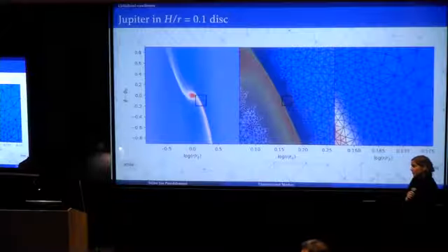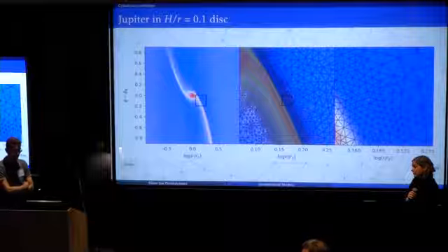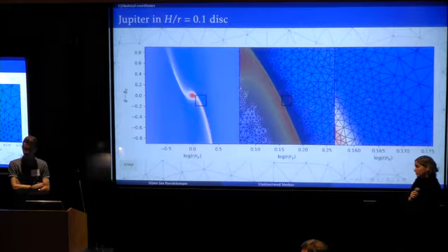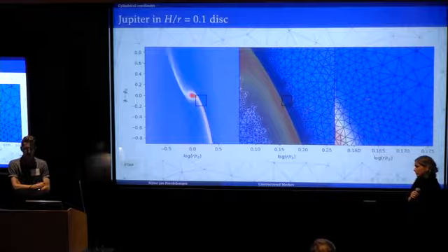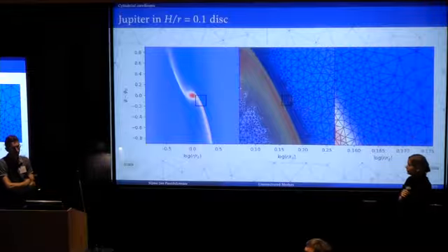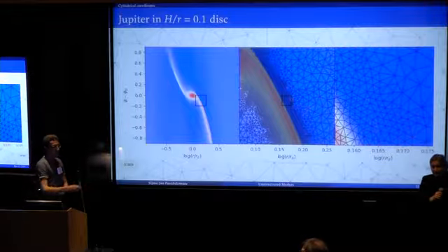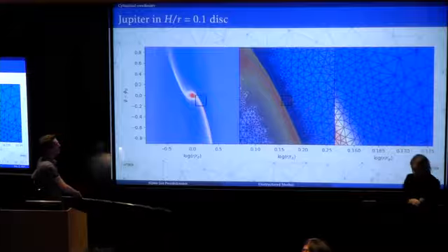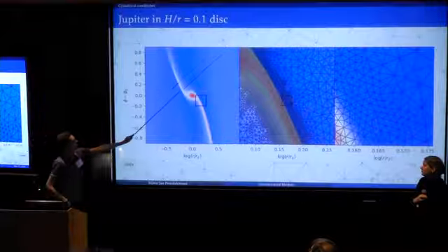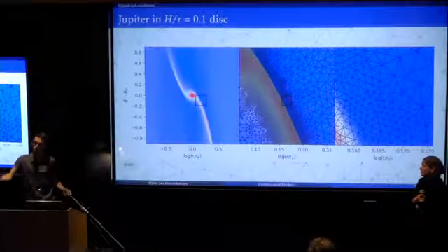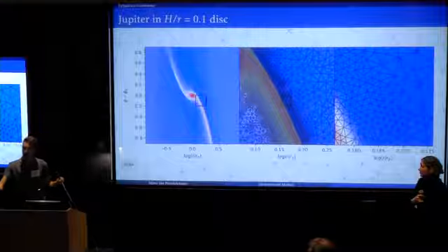But the question was, how do you ensure that it stays a Delaunay triangulation when you increase the number of mesh points? Because if you add them randomly and then don't change the vertices of other nodes, do you not end up potentially drawing really weirdly shaped triangles? No. The way this mesh is generated is you start from, well, if this is a computational domain, you would start from just two triangles, and then you would add points. But the location of the points is dictated by you want to guarantee the quality.